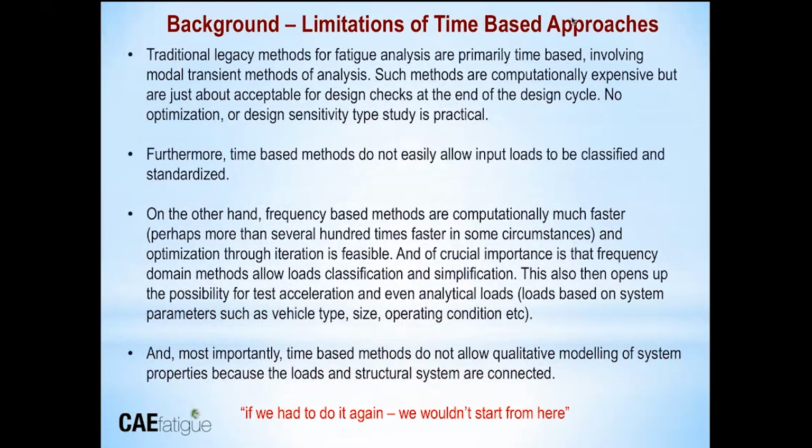And the answer to that is that the frequency domain offers a lot of advantages, and we'll talk about some of those during the webinar. But nevertheless, because of the practical limitations that have been associated with the frequency domain, a lot of things are still done in the time domain. For example, nearly all automotive companies do full body fatigue calculations in the time domain.